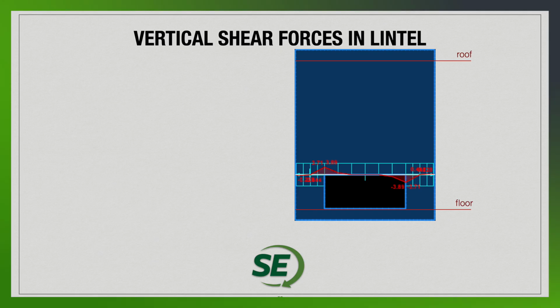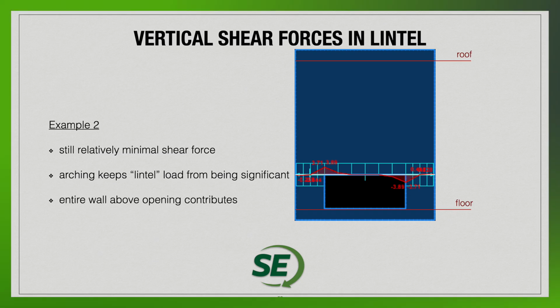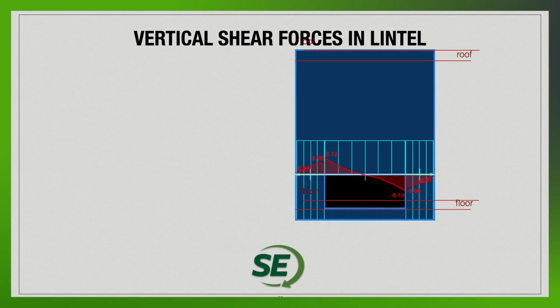Lastly, we can also look at the shear forces that we have in the lintel elements above. So again, you can see those highest at the ends of the lintel. One thing to note is when we do look at finite element analysis, this is going to be looking at the forces across these strips. Again, if I have a limited depth of the lintel, it's going to be smaller forces. If I increase the size of the lintel elements, so that's increasing the actual size of the elements that I'm summing the forces across, you can actually see the forces go up. And that makes sense. Again, we're grabbing a larger area, larger cross section to actually look at the forces.